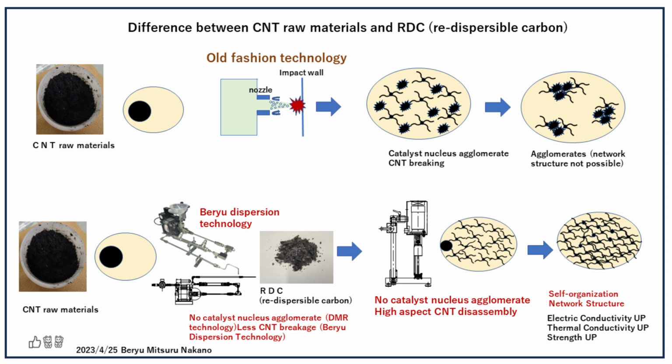This is because the impurities contained in CNTs cannot be removed. It is amorphous carbon agglomerates of non-crystalline amorphous carbon that encapsulate catalysts. We call it dark matter. Its size and solidity are uneven and vary from production lot to production lot. It is also carbon, so it is not counted among the purities. Even if we know the amount of metal catalyst in a 95% pure CNT, no one knows how much dark matter is in the blend.